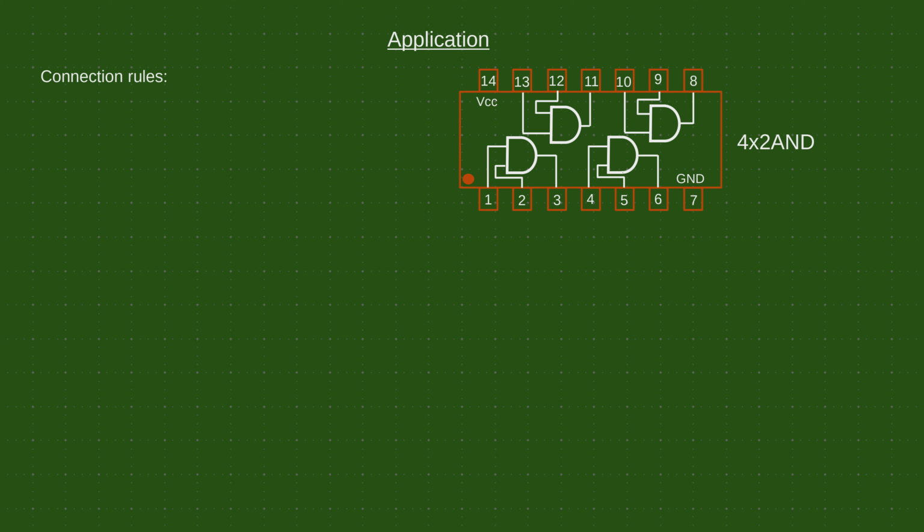But when applying logic gates, you need to be careful how to connect them properly. The first rule, and perhaps most important, never, but never, connect two or more outputs directly to the same point. This will certainly cause a short circuit and probably destroy the chip. A short circuit and destruction occurs when the two outputs are in different states. One is high, and the other low, in other words, a recipe for disaster. And be happy if that is the only damage. Often a destroyed chip causes damage to other components which can be much more expensive. So it is better to be careful.